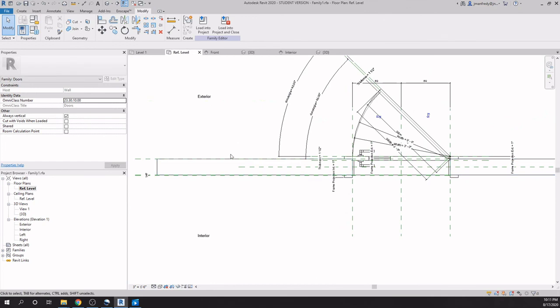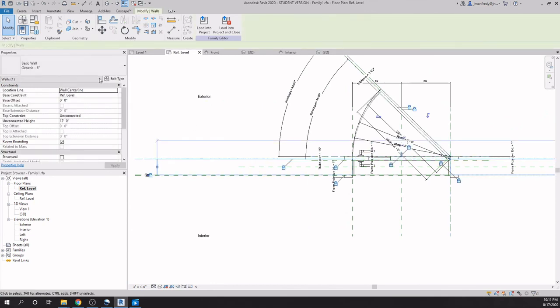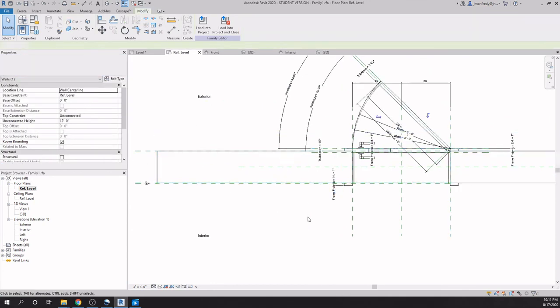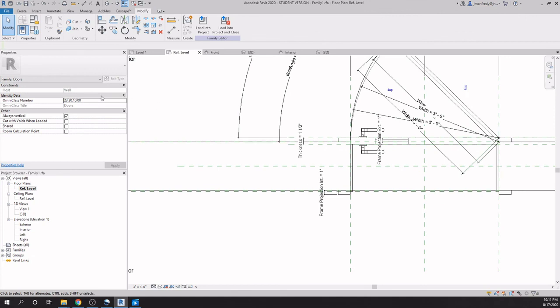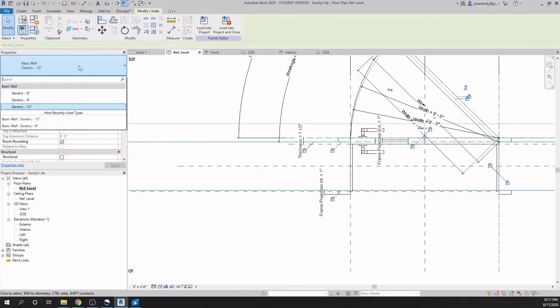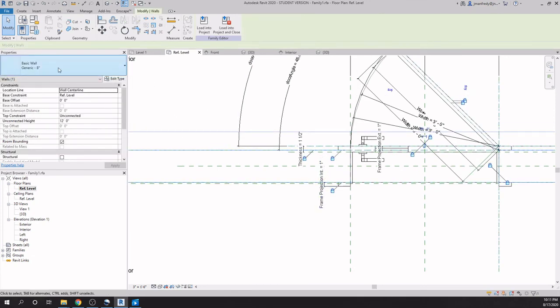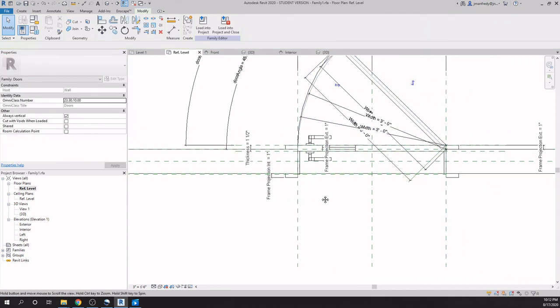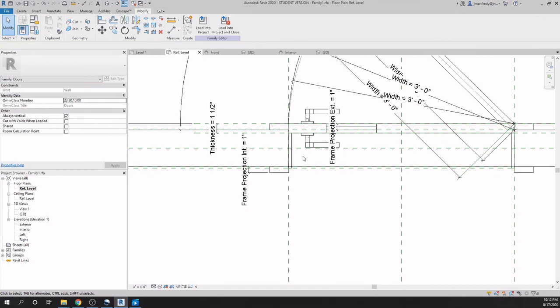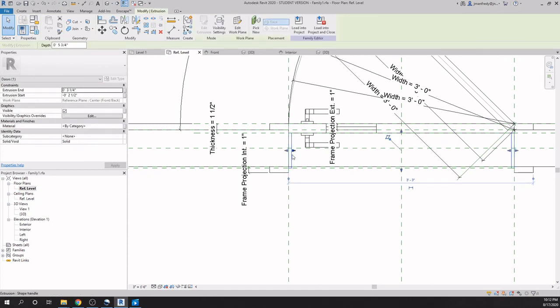Let's test that hypothesis. This wall becomes 12 inches thick. Suddenly that trim gets longer and it follows. It also starts back there by the door. That's working. If this wall got narrower, it's following. If it got really thin, it's following. It's doing its job. The one thing it's not doing is it doesn't have a material assigned to it. So this currently has no materials applied here.